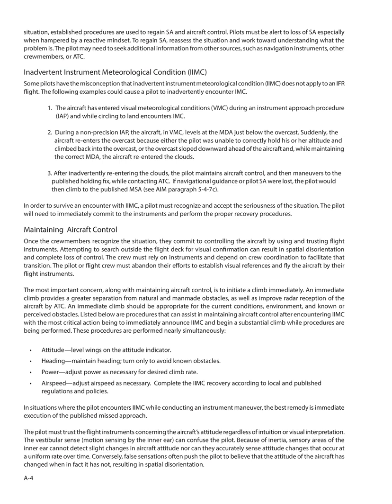Attitude: level wings on the attitude indicator. Heading: maintain heading, turn only to avoid known obstacles. Power: adjust power as necessary for desired climb rate. Airspeed: adjust airspeed as necessary. Complete the MC recovery according to local and published regulations and policies.